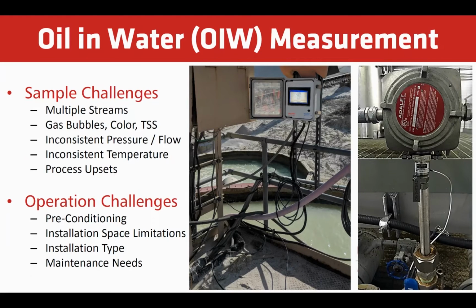Inline installation makes sensor retrieval more difficult for scheduled maintenance. Sampling from bypass lines must ensure the fluid reflects real-time conditions. For these reasons, you should make sure you understand all available technologies.